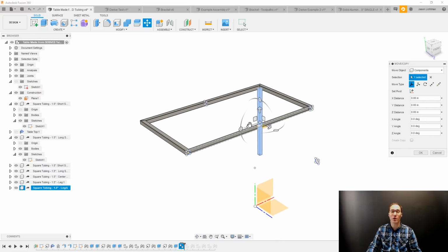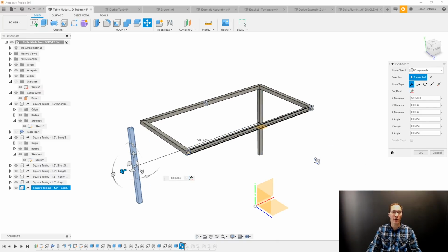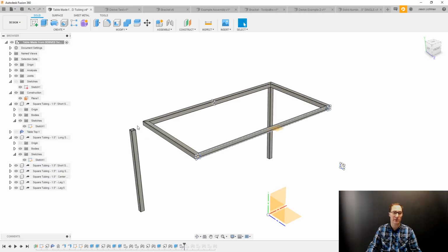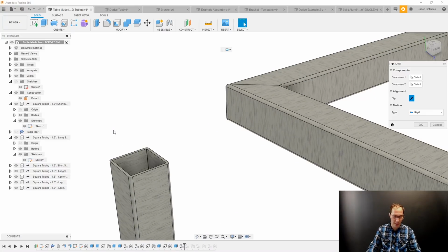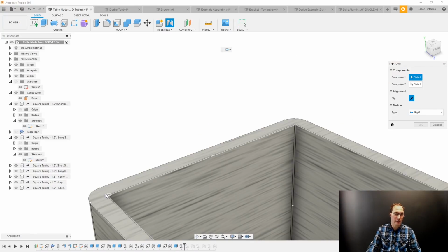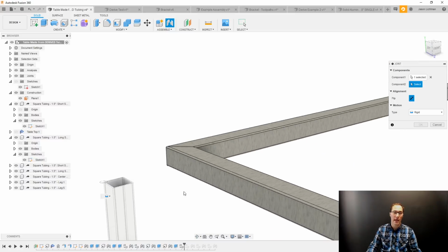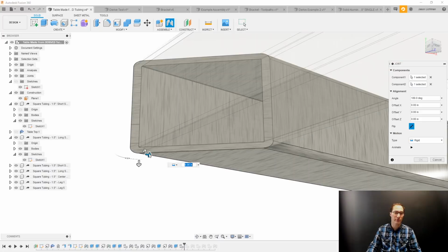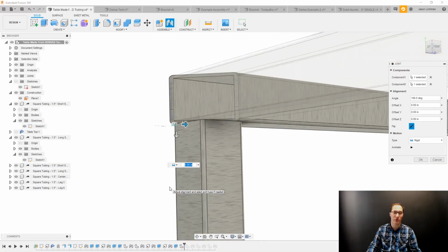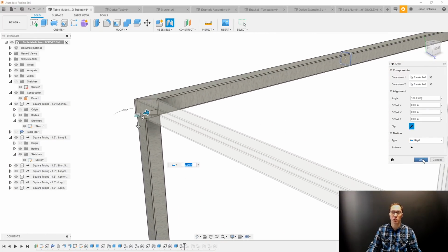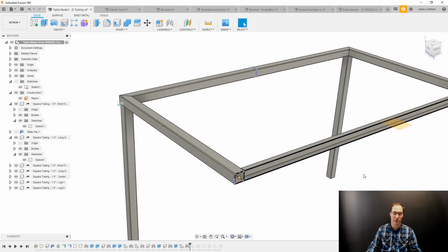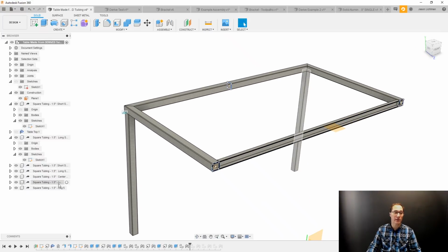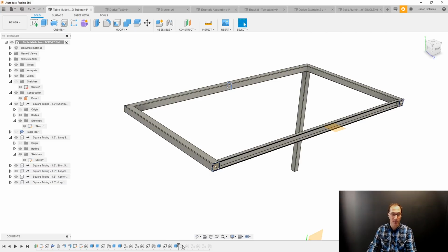And then I'm going to take this and move it off in space so it's easier to use joints. And then I'm going to use a joint. Let's say in this case, I might use this corner, and then I might pick some other corner. This isn't even going to line up perfectly, but it doesn't matter for now. I'm going to use the joints to get this in the right position. Happens to me. And in this case, if I change the length of the leg, it updates all the legs. So that would be, generally speaking, how you make multiple instances.